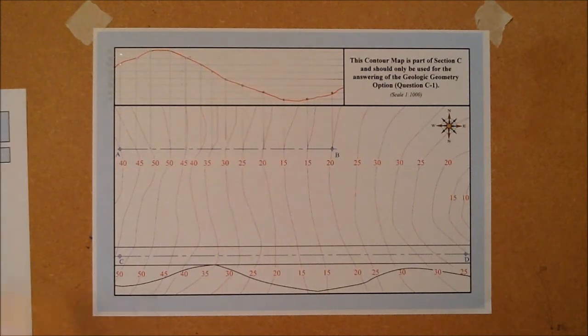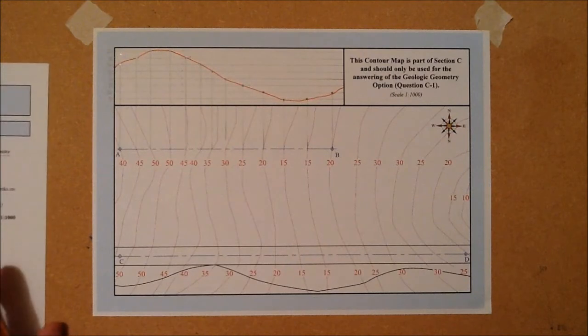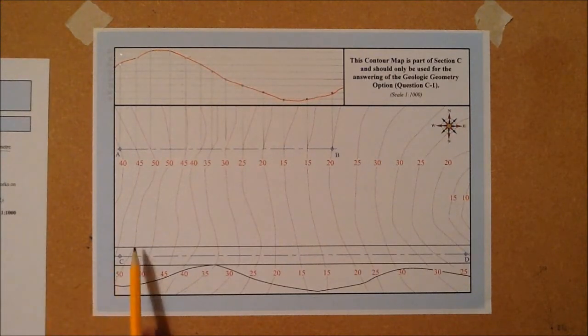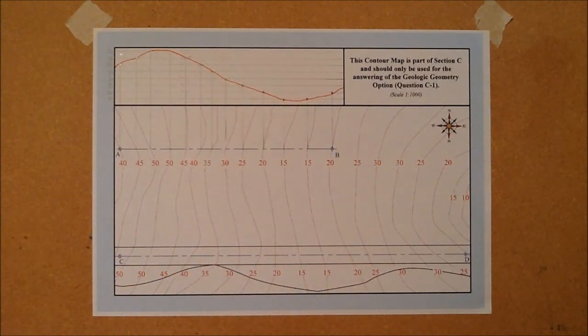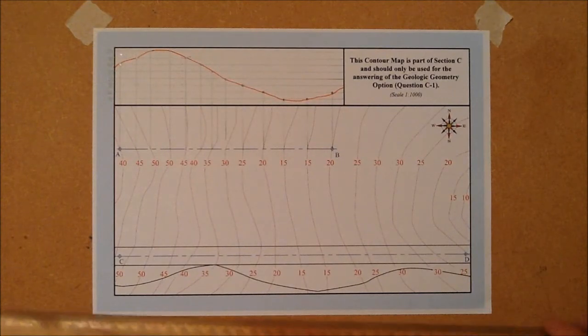So to start off, what information do we need to look at? Okay, so between our contours we know that we have altitudes of 5 metre intervals. Alright, so ranging again from 15, as we said, up as far as 50. Okay, because the roadway itself is actually level, we know that the contours will run parallel to the road.